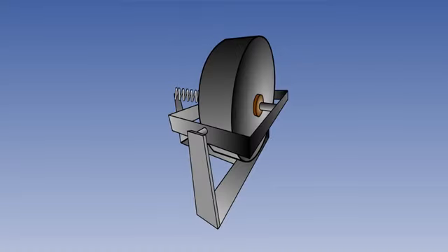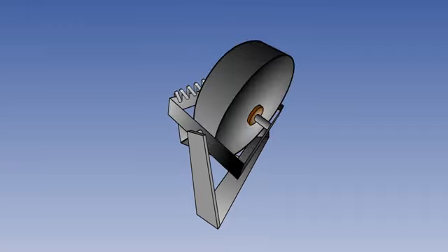The second category of tuned rotor gyros is the rate gyro. With this type of gyro, the gyro is mounted in a single gimbal, and a rate spring restricts freedom of the gyro in precession. The single gimbal allows freedom of movement around 2 axes, one of which is the gyro's spin axis.